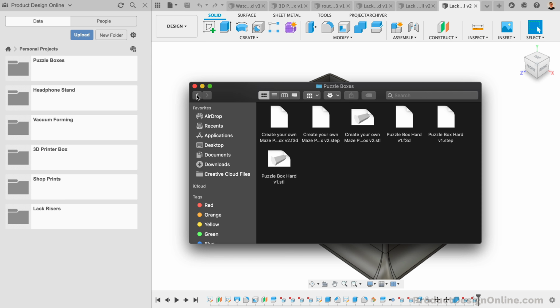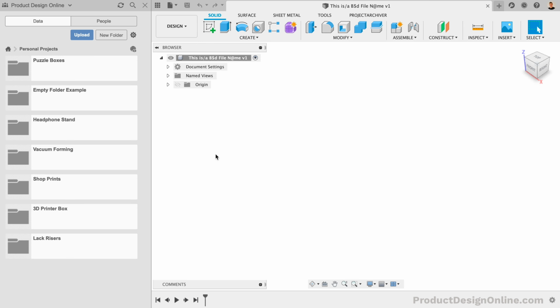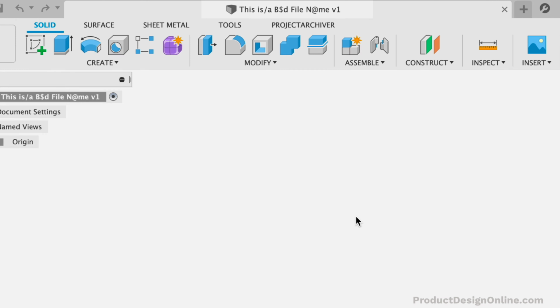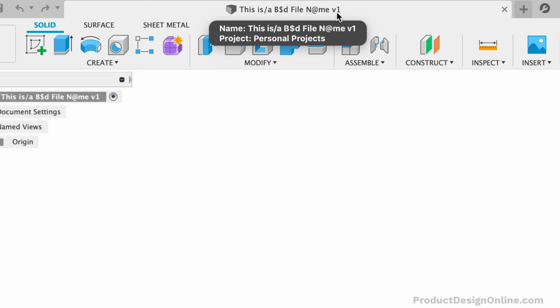Lastly, it's important to note that this is an add-in, so you may run into bugs or cryptic error messages. I want to share 2 common things that are likely to cause errors. First, make sure that none of your file names include slashes or unique characters. This likely conflicts with the add-in code, which causes the add-in to stop working.